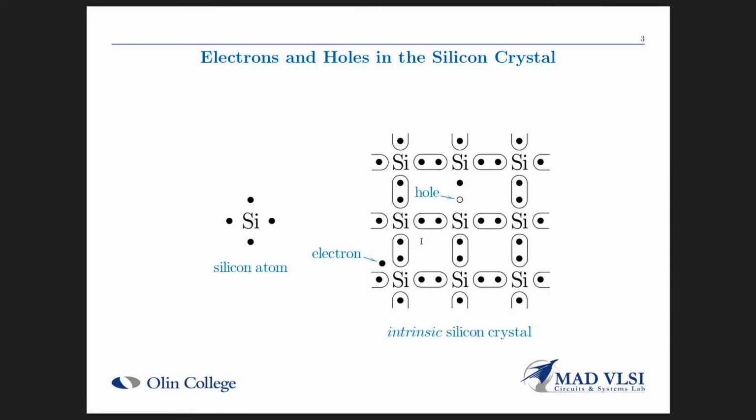And so it doesn't take too many 10-degree increases for there to be a whole lot more electron-hole pairs available than there would be at room temperature. And so if you plot the conductivity of a material like intrinsic silicon, you'll find that it follows an exponential characteristic with temperature.